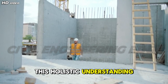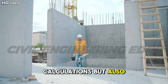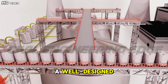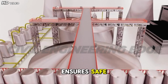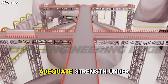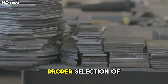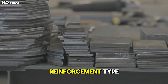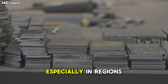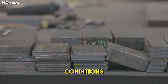This holistic understanding is essential because column performance depends not only on calculations, but also on sound engineering judgment and quality execution. A well-designed, reinforced concrete column ensures safe transfer of loads from the superstructure to the foundation, while maintaining adequate strength under axial loads, bending moments, and shear forces. Proper selection of concrete grade, reinforcement type, and detailing methods enhances ductility and durability, especially in regions exposed to seismic activity and harsh environmental conditions.